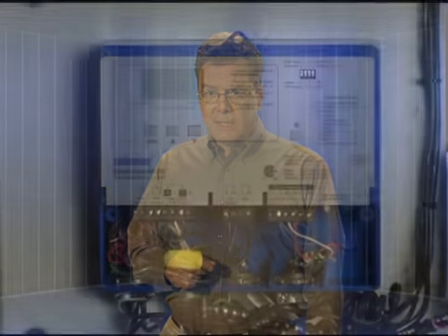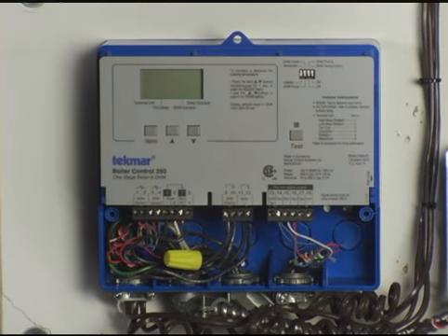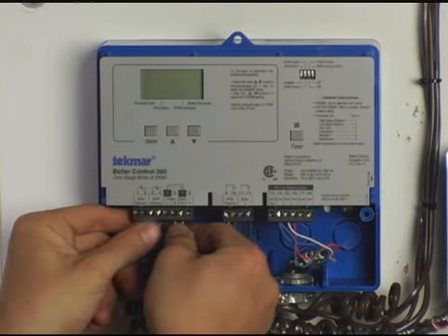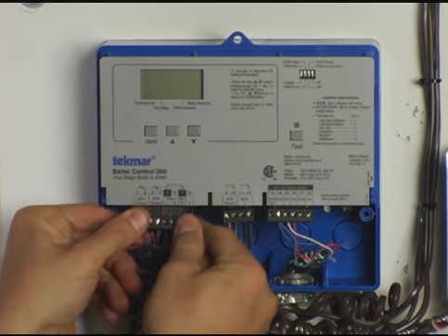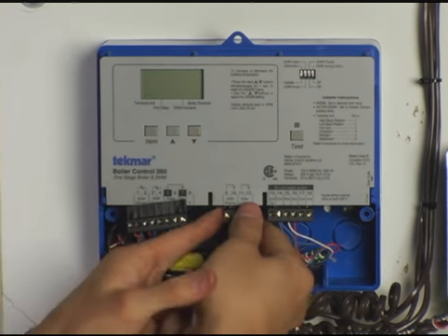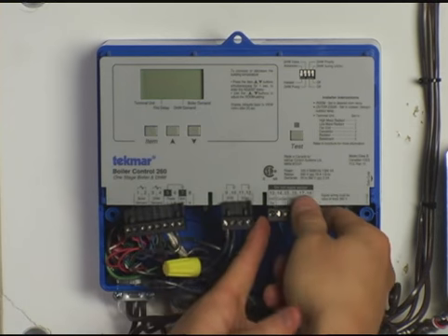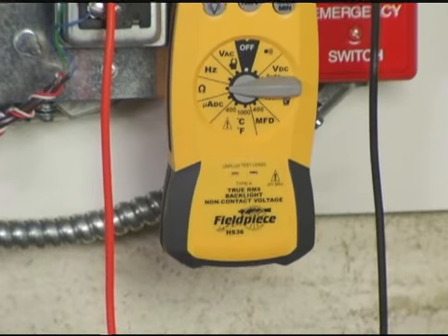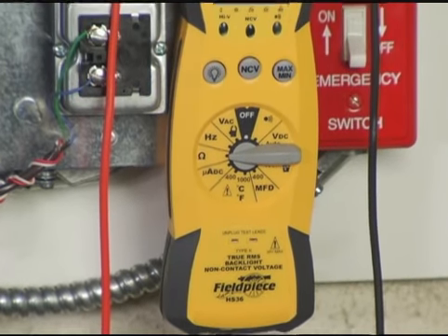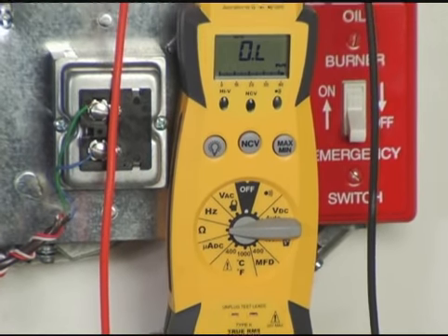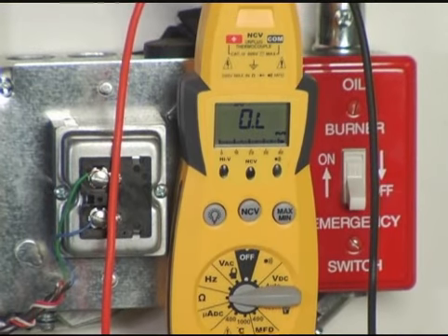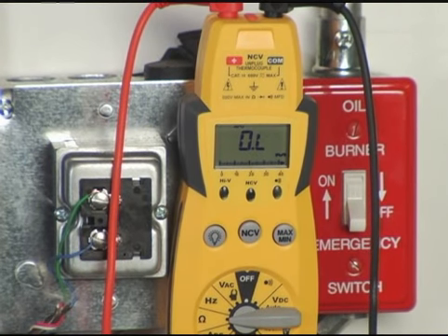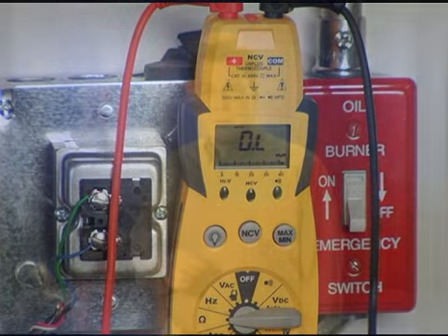It's good practice to verify the installation before putting the control into operation. Each terminal block must be unplugged from its header on the control before power is applied for testing. To remove a terminal block, pull it straight down from the control. A quality electrical test meter capable of reading from at least 0 to 300 VAC and at least 0 to 2 million ohms is essential to properly test the wiring and sensors.